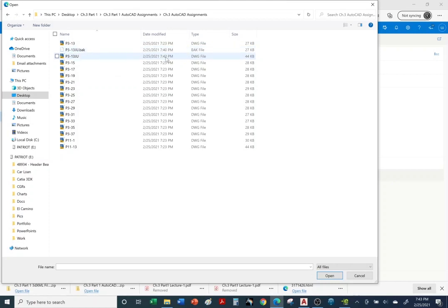So even though it's only 2 minutes older than the final one, if you're going to email me this one as the backup, just in case this one got corrupted, you have to go in there and change the BAK to .dwg. Okay, so you would have to save it as a .dwg file, right? So that way the computer knows to open it in AutoCAD or in Autodesk software. Okay, I don't need to do this, so I'll just leave it as BAK.